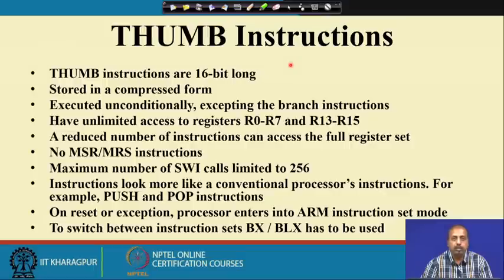I should say that this Thumb instruction set is more close to the standard microcontroller instructions. They are executed unconditionally. So, there is nothing like ADDEQ or SUBLE like that. You can have only plain add, sub type of instructions, and only the branch instructions are conditional, but except that all other instructions are unconditional. Then they have got unlimited access to registers R0 to R7 only and R13 to R15. So, R8 to R12 are not accessible in the user mode.